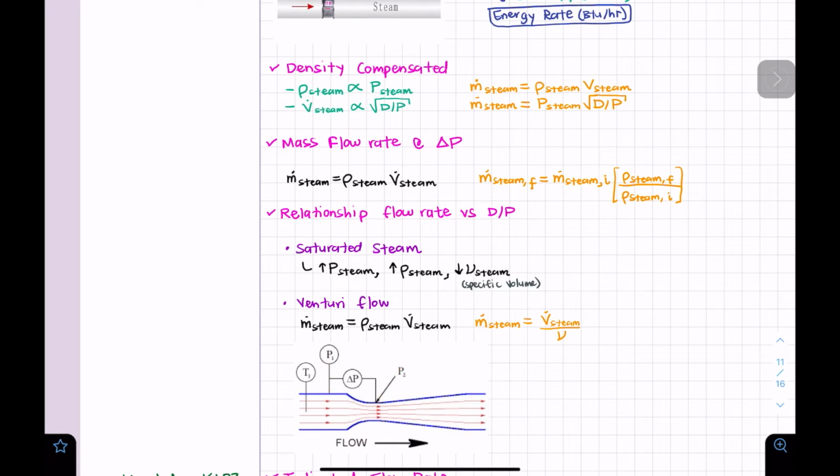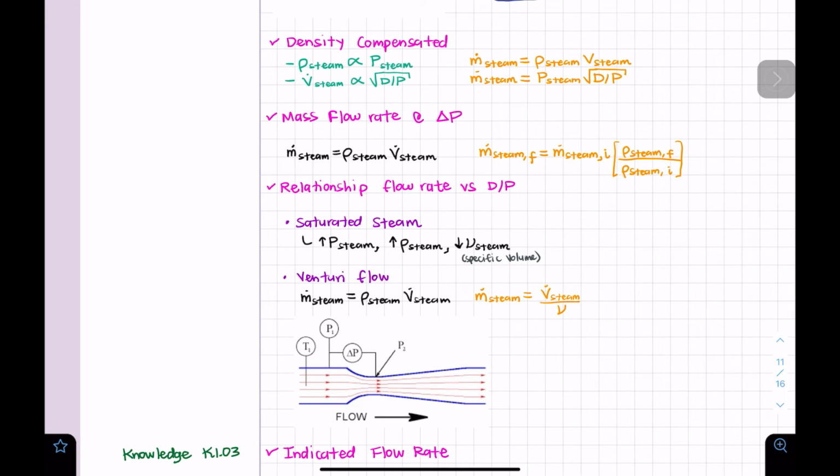The pressure difference is created by reducing the diameter of a pipe, causing the fluid to flow faster. And the fast moving fluid is going to have a lower pressure than the slower fluid in the larger section of the venturi, right? And that's how we are going to measure the venturi flow.